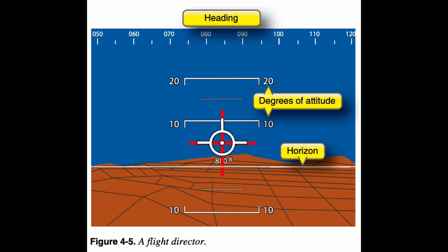Always compare the displays to ensure that all indications agree. If in doubt, fly the aircraft to remain on cleared track and altitude, and reduce automation to as minimal as possible during the problem processing period. The first priority for a pilot always is to fly the aircraft.